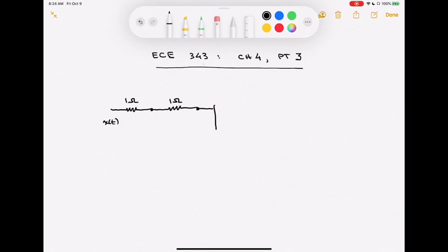So we're going to have an op-amp circuit in here, and it's going to go into the inverting terminal on the op-amp. The non-inverting terminal is just going to be tied directly to ground. Going back to the first node in there, we're going to run a capacitor straight to ground. So we're going to have a capacitor in there, and I'm going to let that be a 1 farad capacitor. And then I'm going to put a resistor coming off that node as well, and that's going to be another 1 ohm resistor. It doesn't have to be this way, just make a convenient set of values.